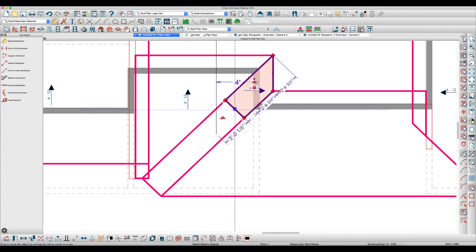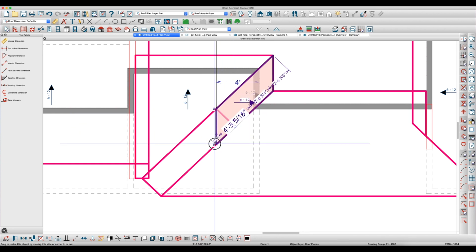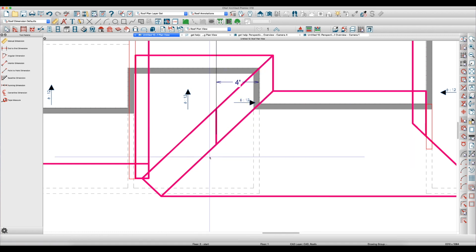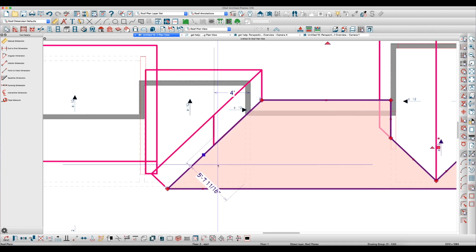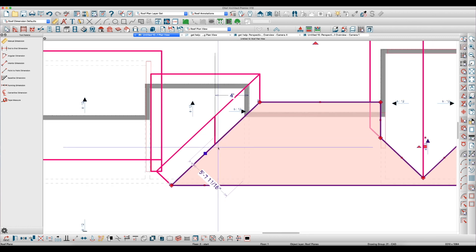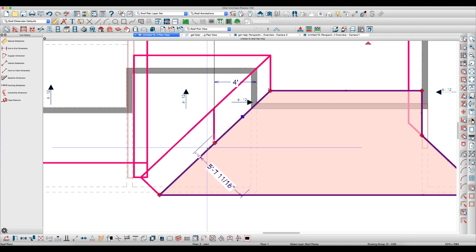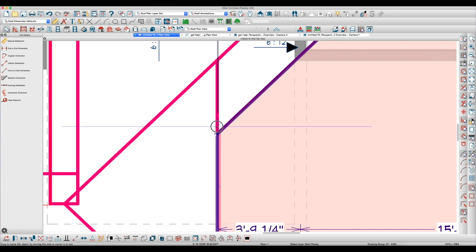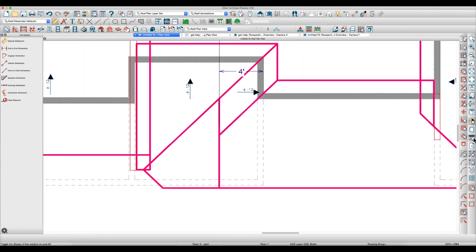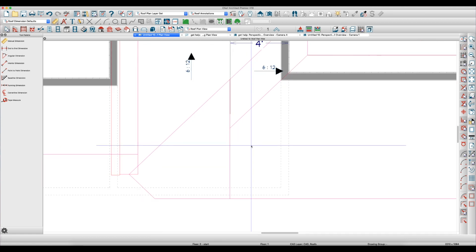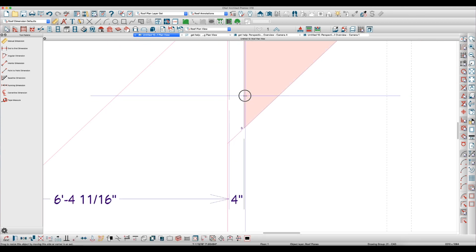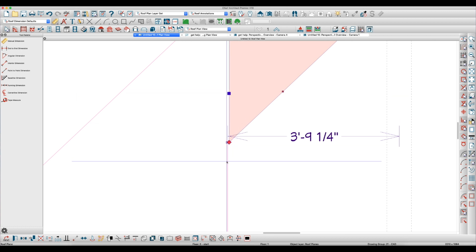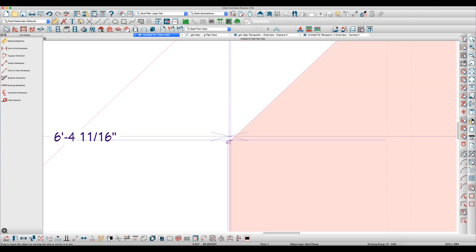gable end. So I'm going to take this roof right here and pull it up so it's plumb right there. And then I am going to use my 3 key, and right where these roofs intersect, click and break it, and then I'm going to pull this roof over. And it's not perfectly aligned, but just take it and drag it till it lines up. I think it's easier sometimes without these lines. See, I don't even have my 4-footer. So there you go. And click here.